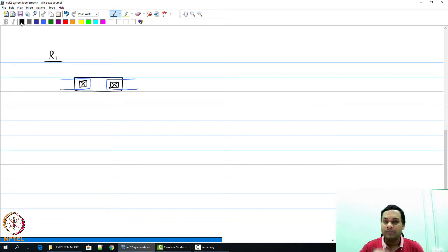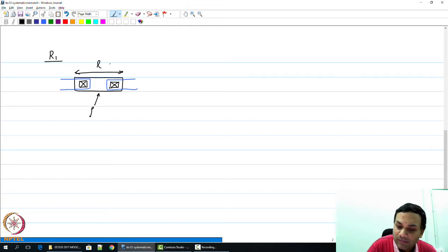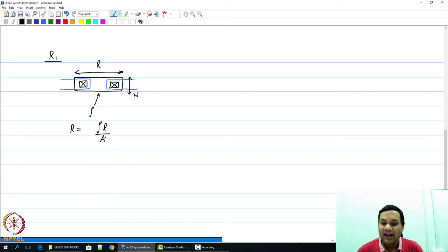So now first I need to note that this diffusion is going to have some conductivity, right, and it has a certain length and a certain width, right, and knowing the conductivity and the resistivity, the L and W, I can say that the resistance is going to be rho L by the cross sectional area A. I should note that if current flows, there is some thickness T for this particular diffusion when the current is flowing in this direction.